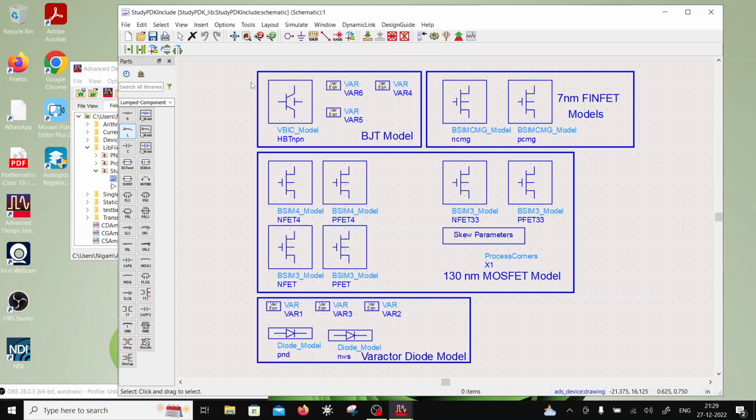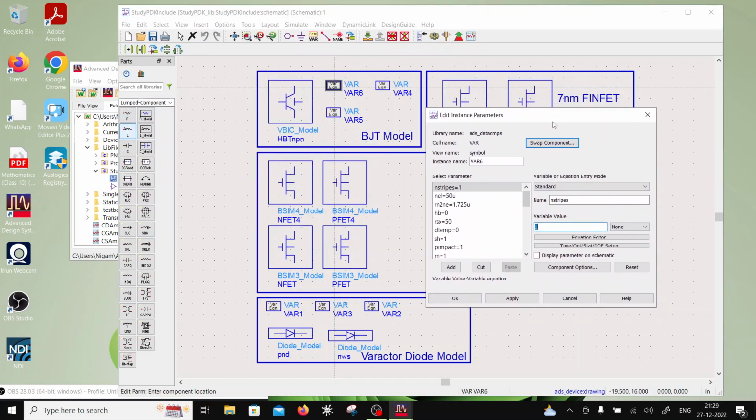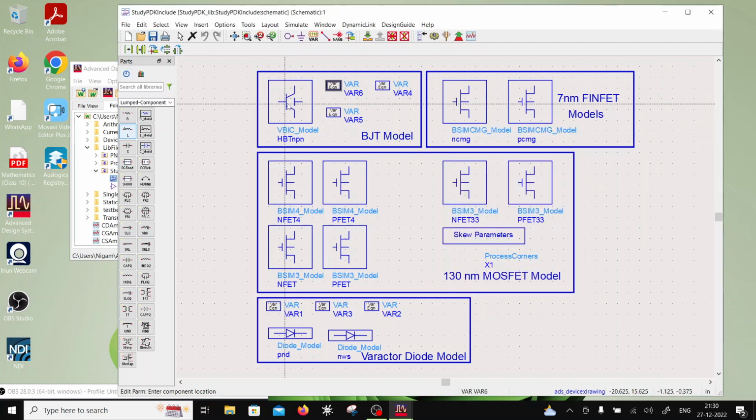Now there is no mechanism at the top level to scale it, so what you can do is add the multiplicity. Here I'm declaring that each finger, each emitter finger, is 50 micron long. You can change here to any number you like, but that will change in the overall design. So I'm going to design everything with a 50 micron finger. And the second thing is that the width of the finger is 0.5 micron, which is fixed for this process. So one finger is 50 micron long and 0.5 micron wide. So that's what we are going to use for a model.